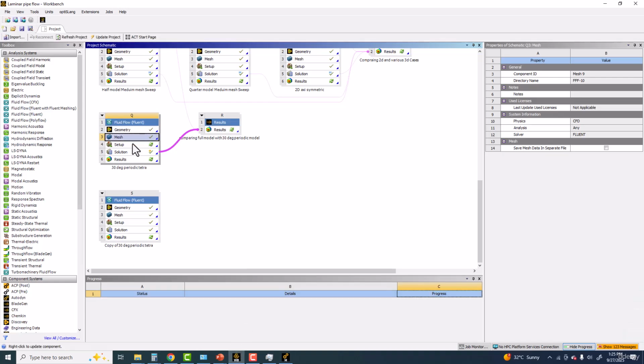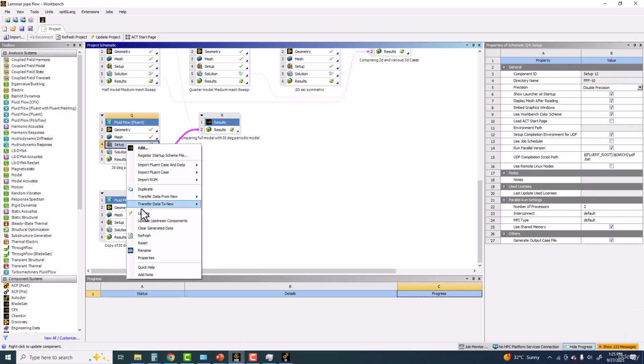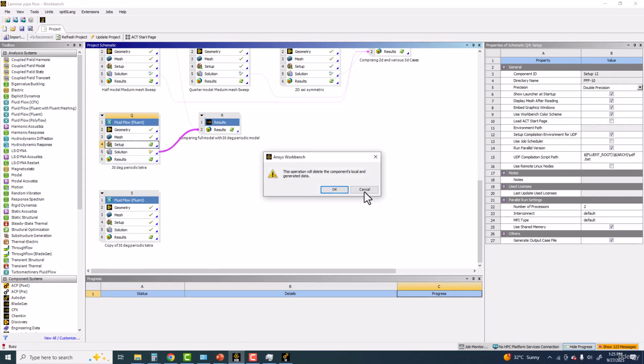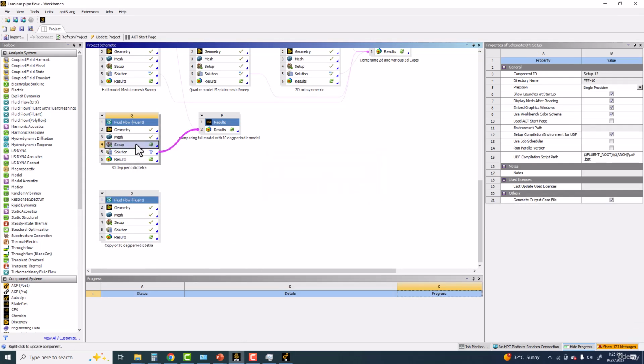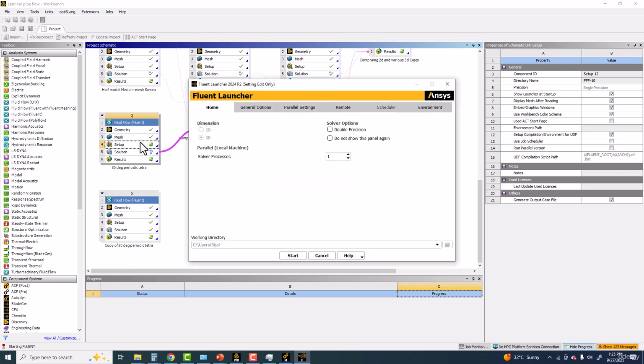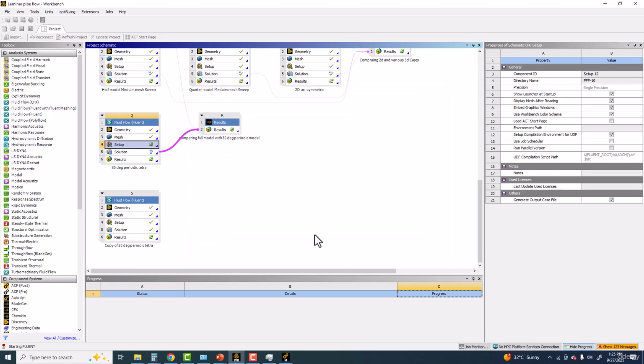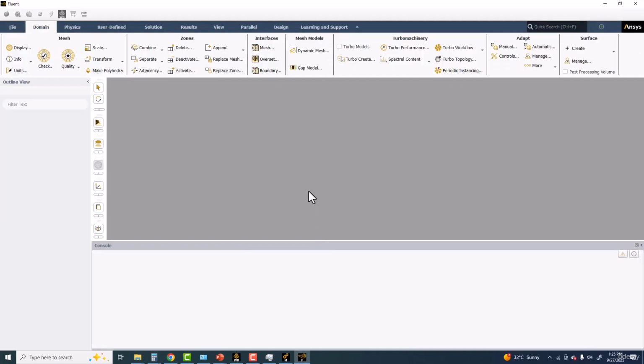In this step, I will show you completely. So I will reset the Fluent part and I will start from scratch so that I can show you the different commands here, because putting the boundary conditions and the material properties is very simple. There are only 2 or 3 things to be put there: laminar flow, material properties, the boundary condition like a velocity inlet. The main and important thing is the periodicity in the mesh that has to be done.